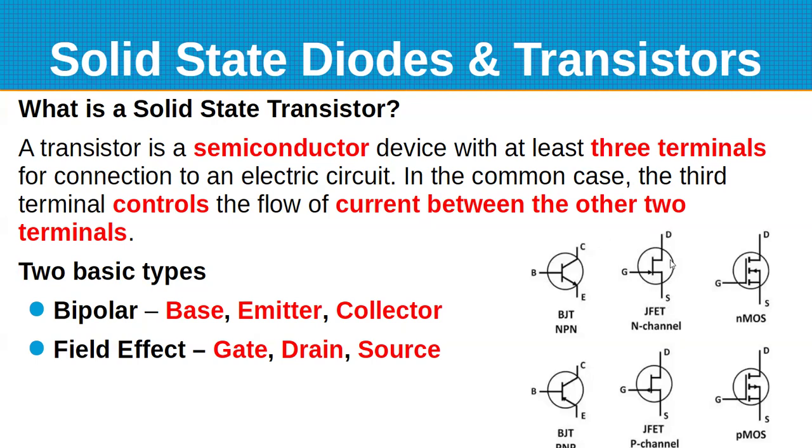And now these are labeled because electron flow comes in the source and goes out the drain, just to confuse you. So they got wise when they invented the field effect transistors and started talking about actual electron flow. It works similar, except there's no current that flows between the gate and the source. It's strictly the voltage because it creates an electrostatic field, and it's that field that controls the current flow between the drain and the source.